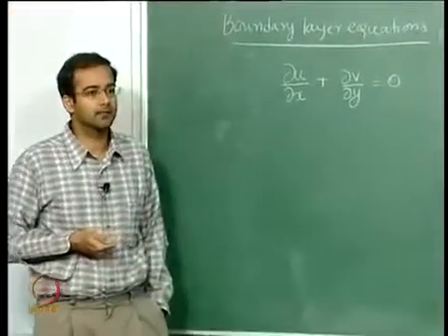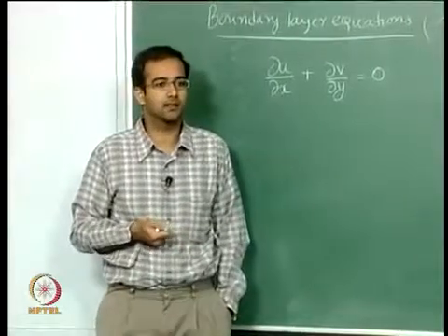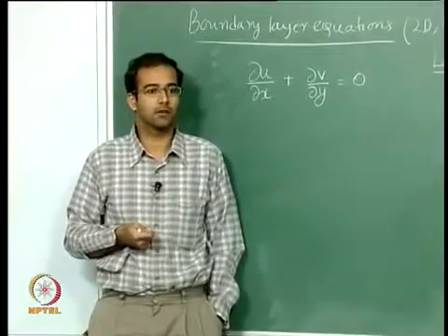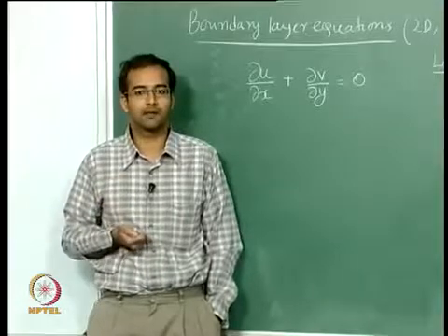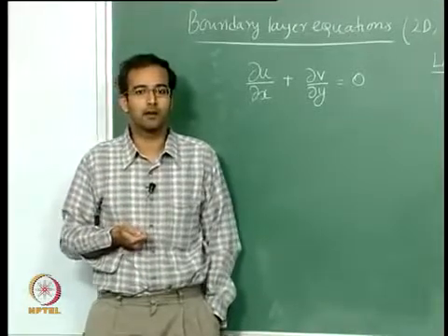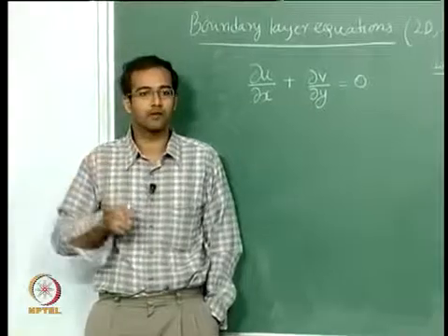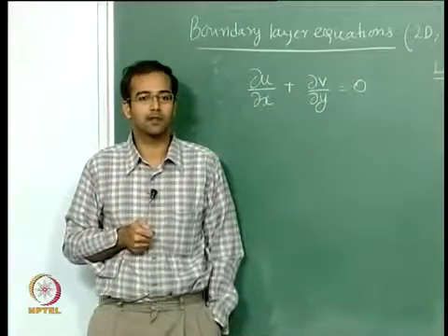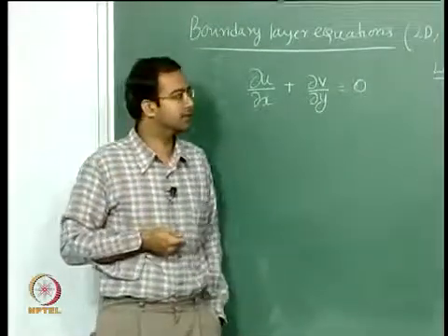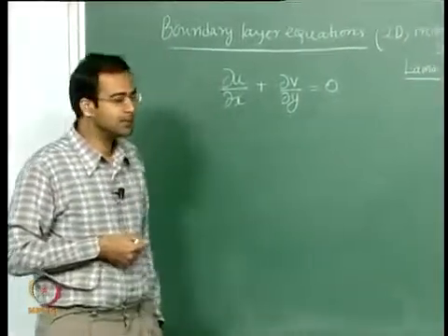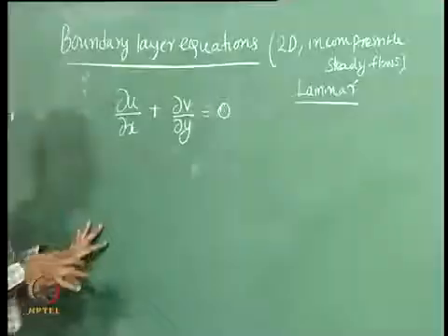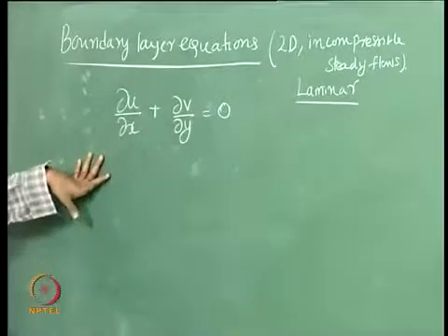This is a very important issue, as most practical flows are turbulent. If you solve the Navier-Stokes equations as they are, there is no problem, but most of the time you cannot resolve all the scales, and therefore you have to approximately model what are called averaged quantities, and that's where the RANS equations come. So far we have not discussed those things. I am just looking at plain Navier-Stokes equations and approximations.